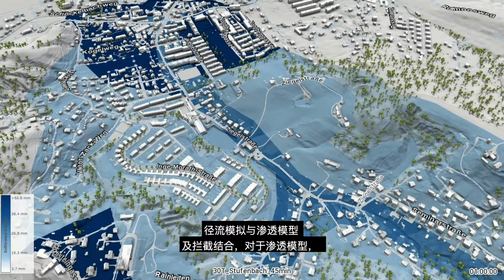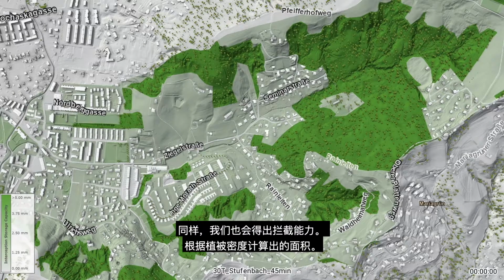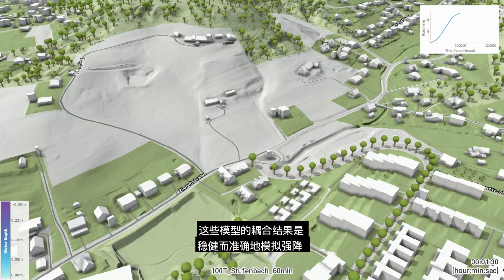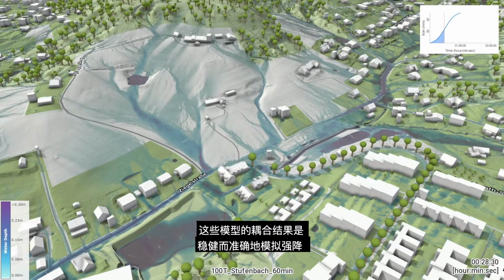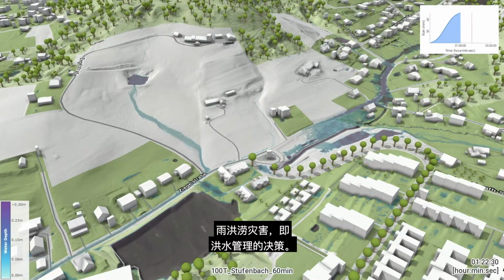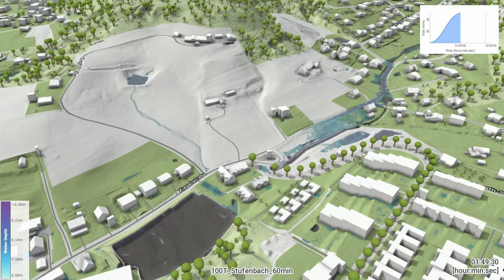For the infiltration model, we derive the infiltration potential of the soil from the input data. Likewise, we derive the interception capacity of an area based on the vegetation density. The coupling of these models results in a robust and accurate simulation of heavy rains and flash floods that supports decision-making in flood management.